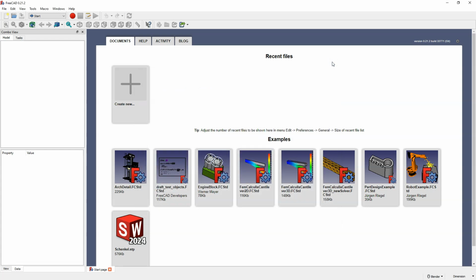We don't use these add-ons and move on to FreeCAD, and FreeCAD is a 3D CAD system. It is a system for technical 3D modeling, and in 3D CAD systems, in this class of systems, we create parts with regular shapes with specific dimensions. That is, here we create such technical parts rather than freeform parts like figurines. And we can approach the creation of such parts in several ways, but one popular way of working in 3D CAD systems is to create a 3D model based on 2D geometry. That is, we create a 2D sketch on the basis of which, using 3D solid creation operations, we create a 3D solid. And in FreeCAD we can also work in this way.